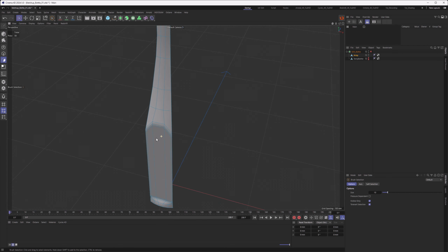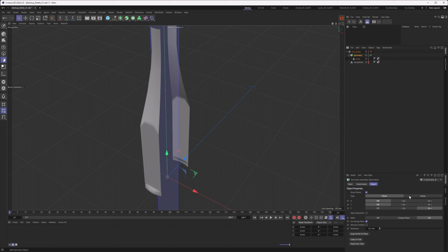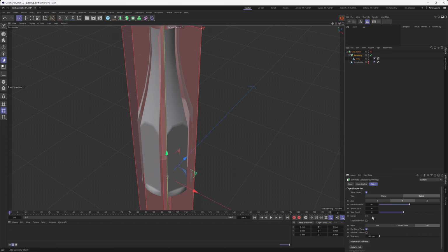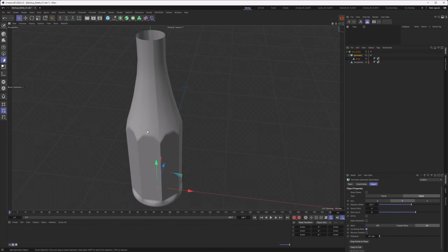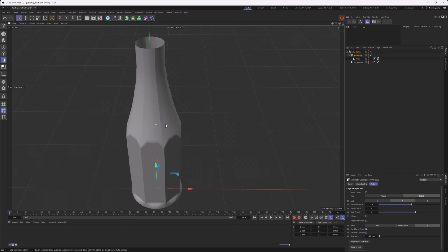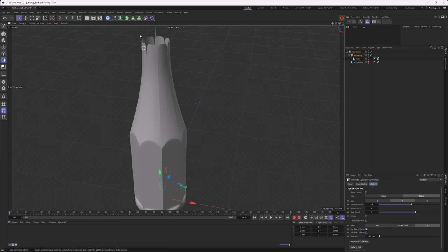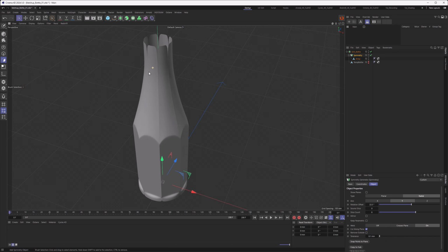Of course, this is acting on an axis right now, but there's more options. So we can use radial symmetry, go for the slice count, and we have 8 slices. And then go for the offset in the rotation and hit the 22.5 that we established in the beginning. And now we have a radially symmetrized object here. There are 2 things I want to do. First of all, the show planes I want to turn off. And now you can see there's cuts all over again.